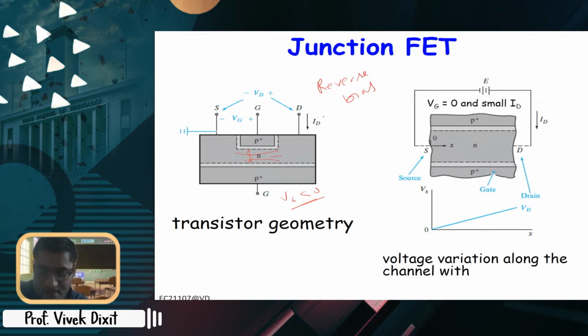One is called source, the other is called drain. The source is basically sending the carriers. The carriers here are electrons, so electrons will move from source to drain. That means the drain voltage has to be positive, so a positive VDS will be applied in this case.